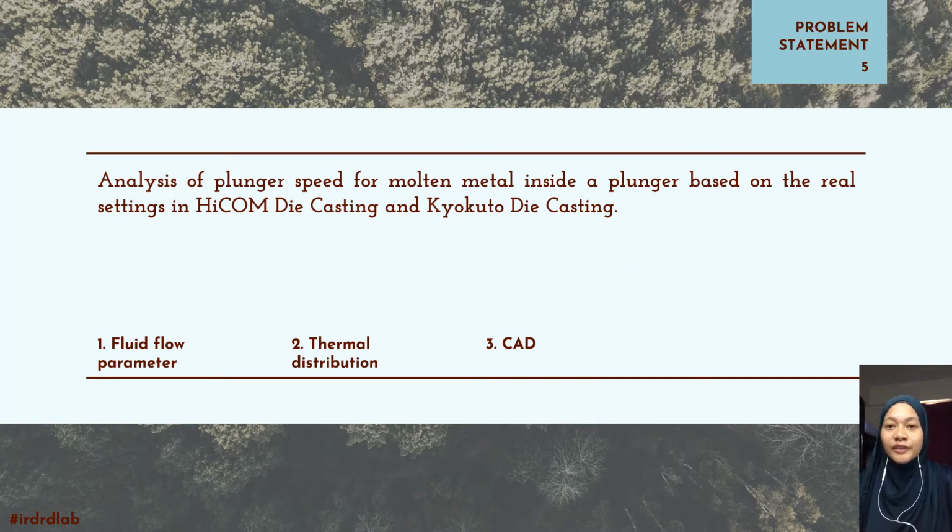With the technology of die casting that may produce excellent cast parts, there are always risks of defects forming due to the high injection rate. The occurrence of defects is usually due to porosity. The frequent casting defect is caused by the imbalanced fluidity behavior of molten metal, as well as the inconsistent thermal distribution in the plunger. Hence, gas bubbles are not fully released and are entrapped during the injection procedure, causing porosity in the products. Injection speed in the plunger is one of the main features affecting the development of porosity.